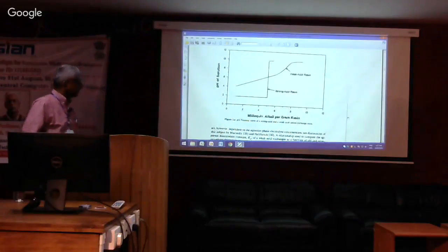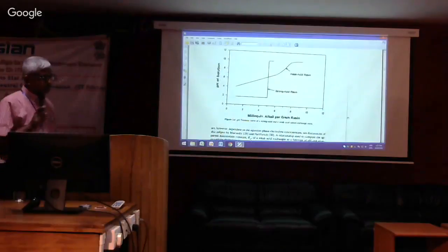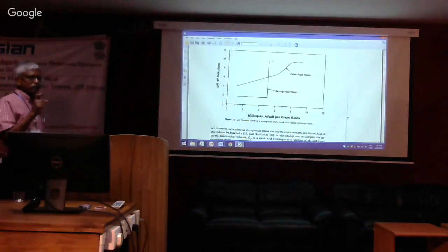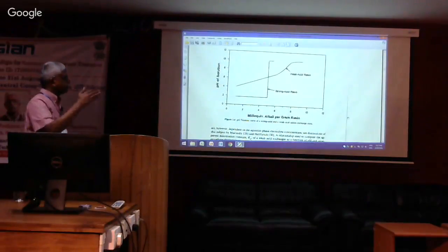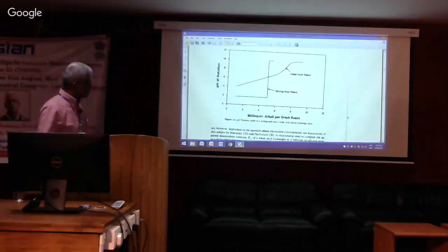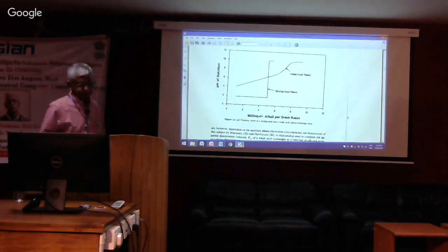But if you want to use a weak acid, let's say for hardness removal, as we just heard, then you have to be very careful. What is the pH that you are using in the exhaustion cycle? And now you may have to manipulate the pH because if your, let's say, alkalinity is very high, then you may have to do certain manipulation. But with strong acid, there is no problem as such.